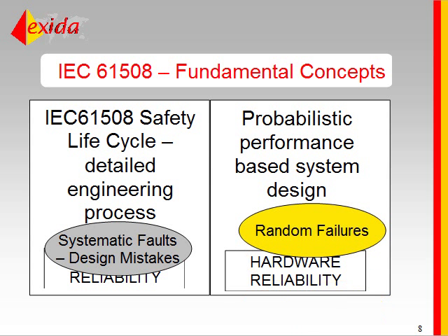What we mean by that is we need to evaluate the probability of failure of a particular safety instrumented function. Of course, in order to do that, we need to know what the failure rates are as a function of failure mode. It's also very important that we understand how good any automatic diagnostics built into the system are, because automatic diagnostics can convert dangerous failures into safe failures, and so forth. We'll be talking about that a little more as we go through.